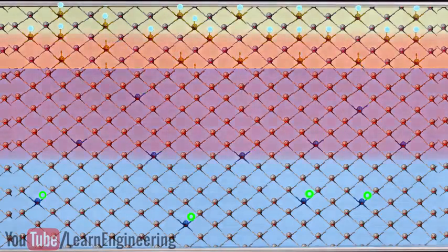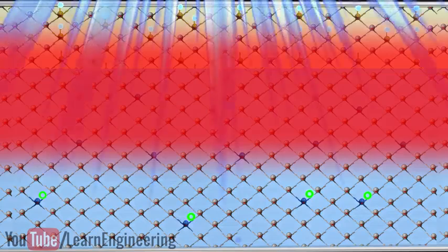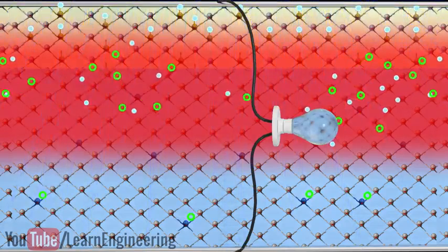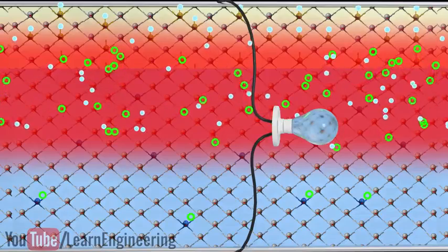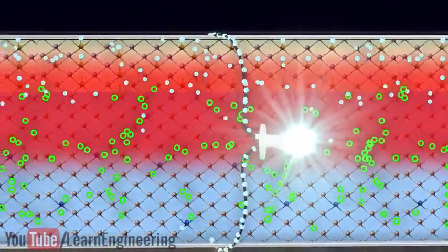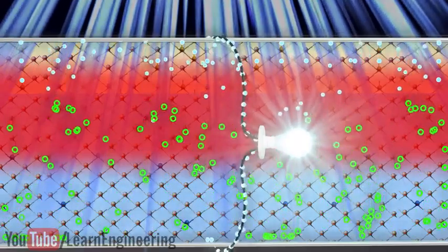You should note that the thickness of the depletion region is much higher here compared to the previous case. This means that, due to the light striking, the electron-hole pairs are generated in a wider area compared to the previous case. This results in more current generation by the PV cell. The other advantage is that due to the thin top layer, more light energy can reach the depletion region.